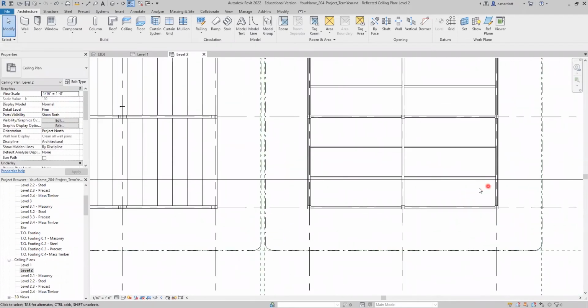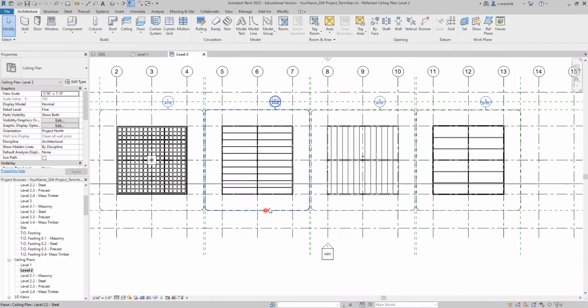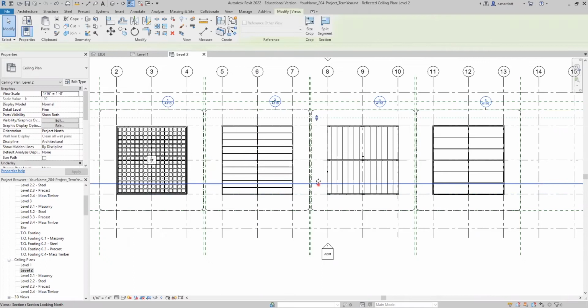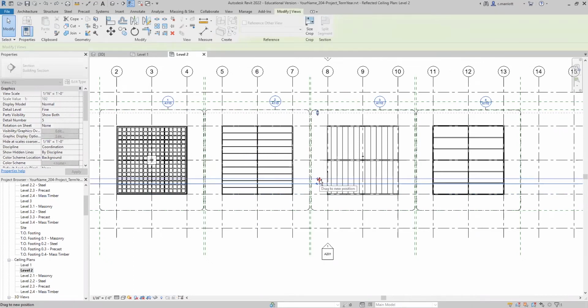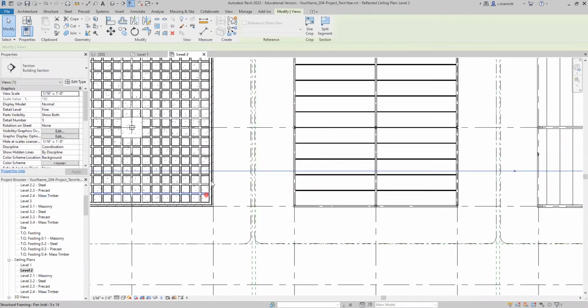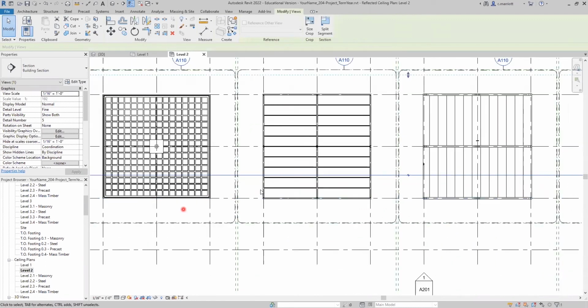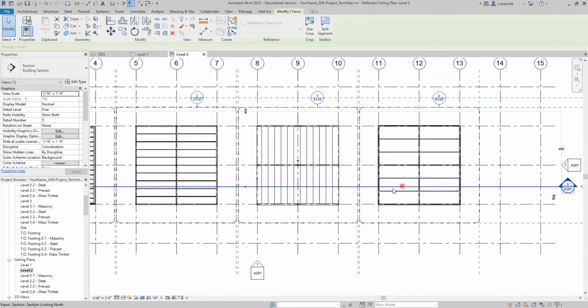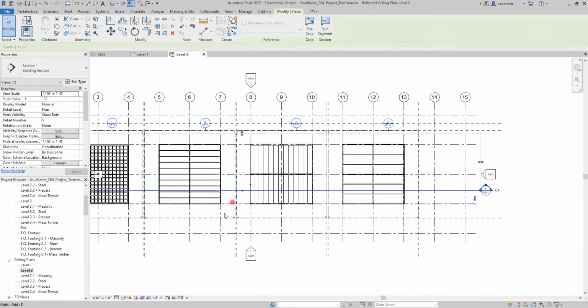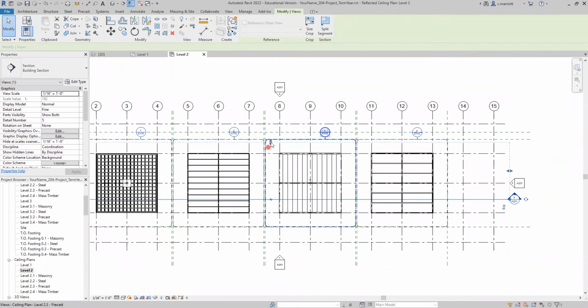This is a little bit close, and so I'm going to look for a place to move that so I have a little bit more space between the structural element and what I'm showing. I'm shifting it up so it's in the center of the waffle slab. So 1, 2, 3, the fourth one, and from there it looks like I have a pretty clean area to view across the whole section. Now you can see everything that is between that section cut and these two arrows will appear in the view.